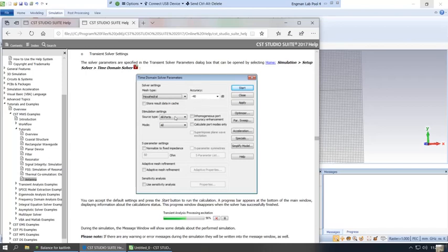And in this case, the source type is all ports, because we only have one port, because this is an antenna and it's radiating. When you get into things like transmission lines or more complex structures interacting with each other, you'll need to define the source that is being excited, is what that means. So all ports, doesn't really matter. You could also just say the port that it is.